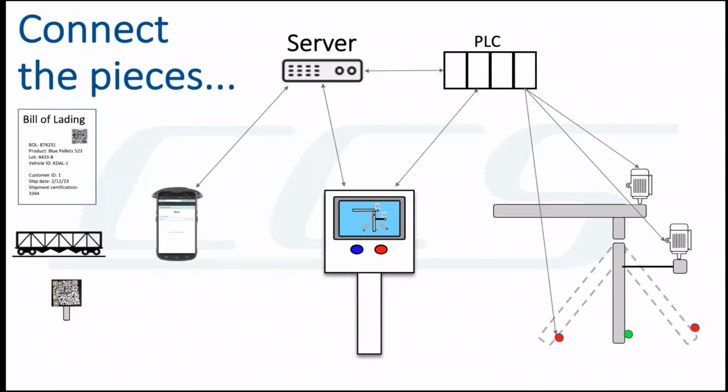And if you look at our website, cates.com, and go to products and pick TransferMinder, there's a little chart. It's not super specific on the costs and the options, but it shows you a progression from just scanning the rail car to identify what they are, all the way up to integrating with your PLC and your HMI, things like that. So there's several steps in between. If you didn't have a PLC, you may want to start adding things like that, and maybe a small PLC with a few limit switches. It really depends how much bulletproofing you want to do to prevent unloading problems or mistakes.